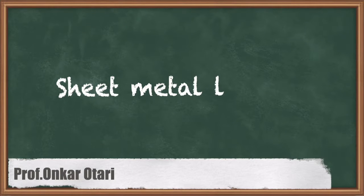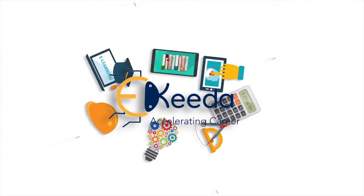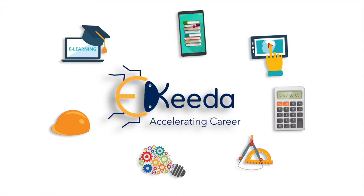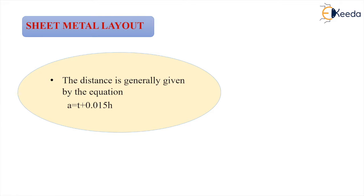Now students, we are going to understand the sheet metal layout, also known as the scrap strip layout. Basically it is a layout by which the blanks are produced from the sheet such that the percentage utilization of the sheet is maximum.